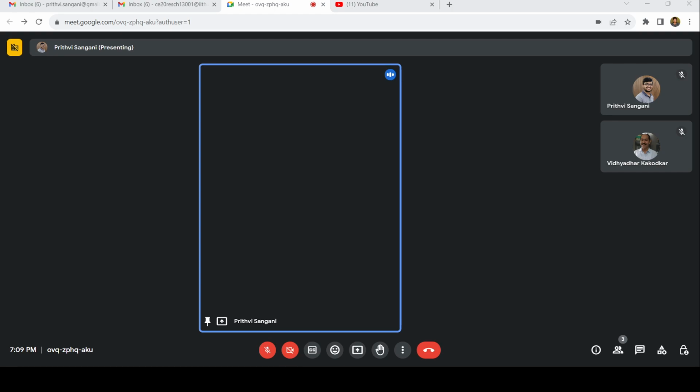So what happens? With this you can simply try to formulate your internal forces. I'll just write the internal forces only for this truss one. For the rest of the truss, it's easy to find out the internal forces, so I'll just leave it for you. So let me write the internal forces here. This is 2.3 kilonewtons. This is 50. So this is 45 degrees.